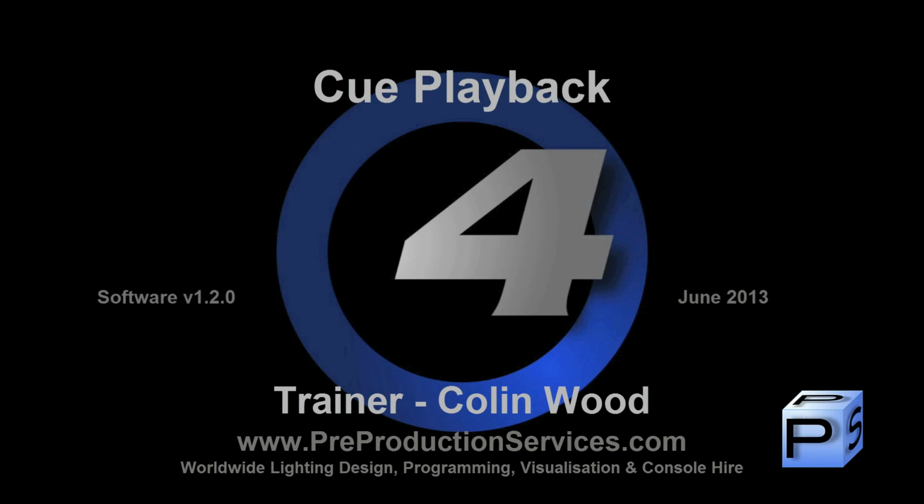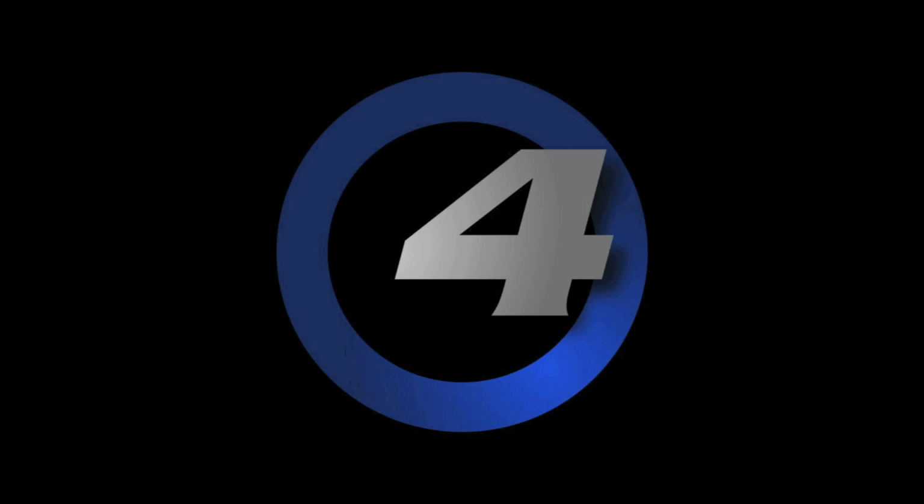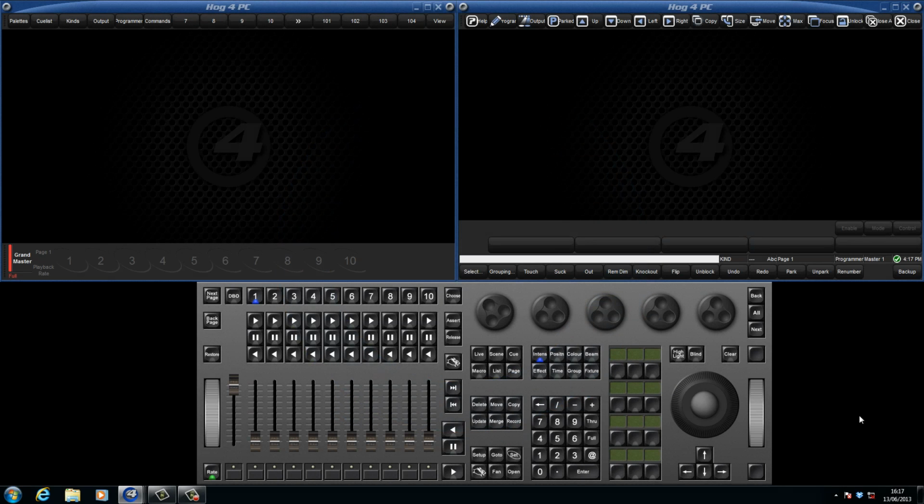Hello and welcome to this HOG4 tutorial, which will look at the playing back of cues and some of the cue list options, as well as how to adjust the playback rate on the console. The playback bar is found at the bottom of the left-hand display. When empty, you can see numbers 1 to 10, and these correspond to the physical playback masters. We can move lists, scenes and groups onto the playback masters.